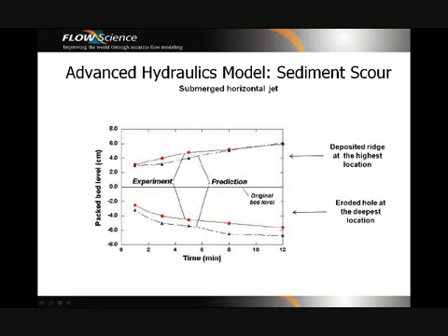Remember that the scour lift model is empirical, and there is a parameter that represents a probability that the particle of sediment is lifted away from the packed bed interface. Adjustment of this value may be needed to more accurately represent the lifting process at the packed bed interface.